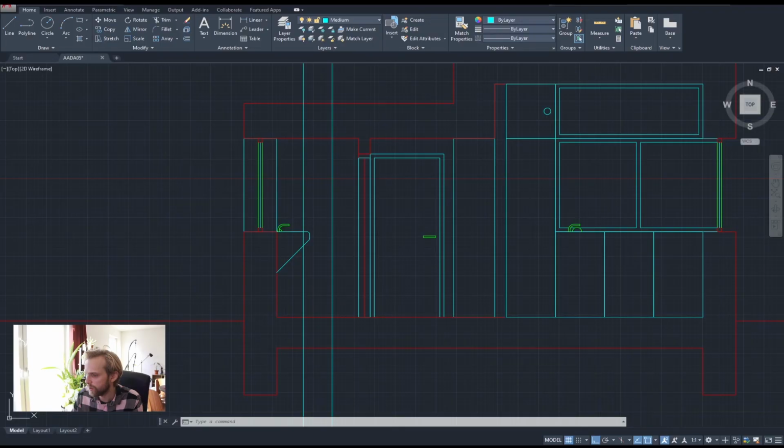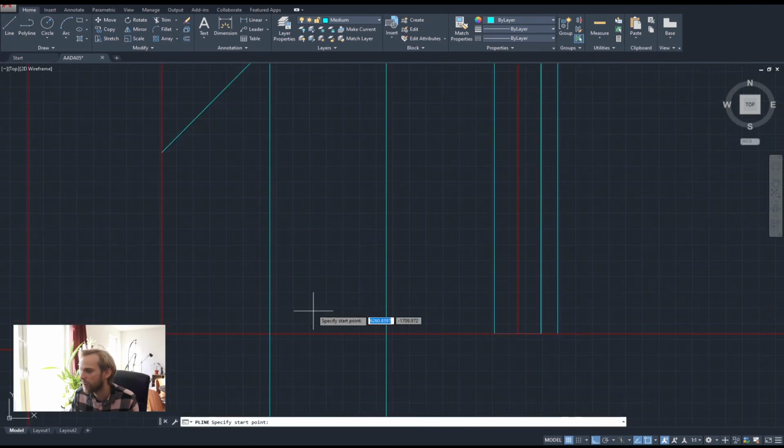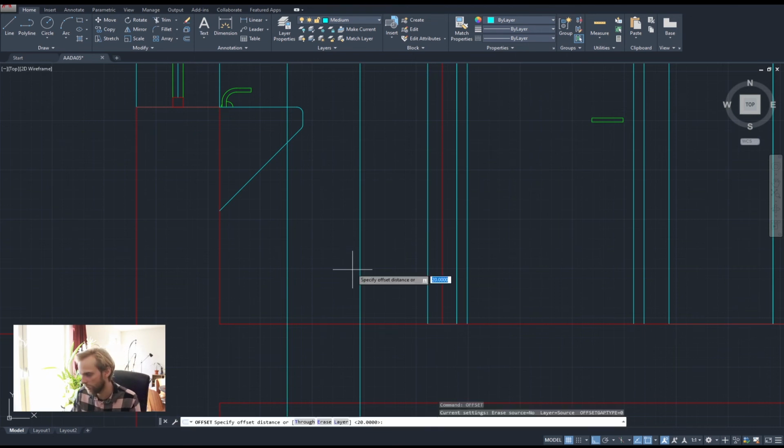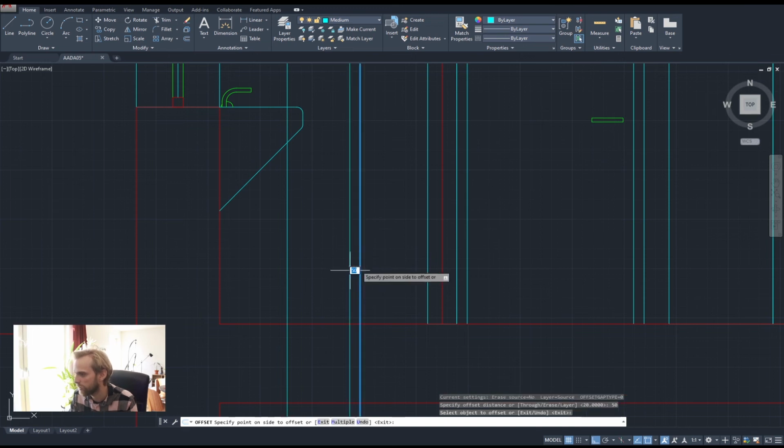That's good to know. Where's my AutoCAD? How do we do this? So there's going to be a line here. It needs to go down and in. Okay, so let's do an offset by how much it's going to kind of go in. Let's say by 5 centimeters, like that, like that.